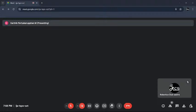Joint two is also a revolute joint, which can revolve around the z-axis with a specific number of degrees according to each and every manipulator's design. And joint 3 will be the translation motion, that is the prismatic joint. The manipulator can extend its end effector or contract its end effector when needed. So the advantage will be high speed capabilities, and you can use it in fast operations.